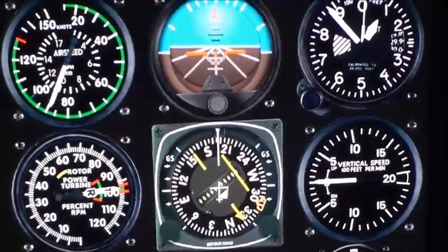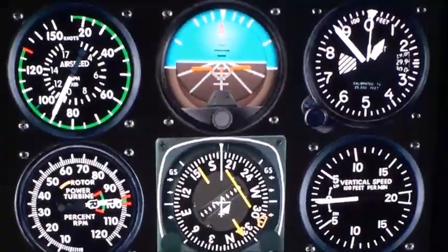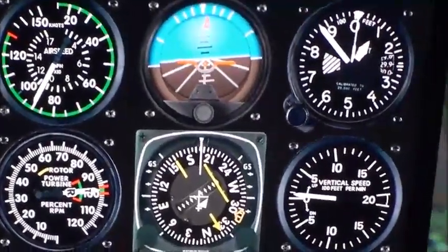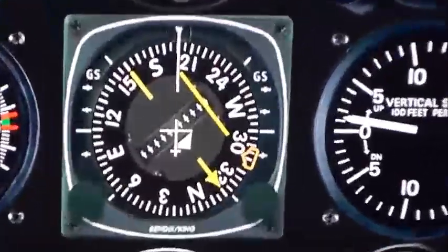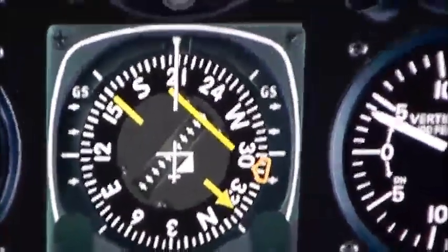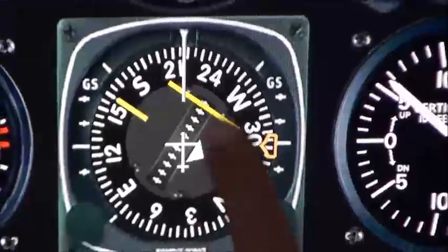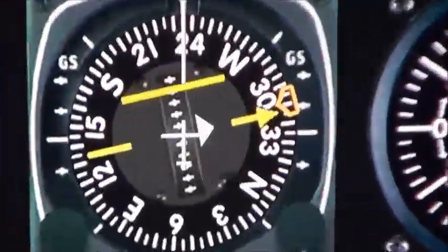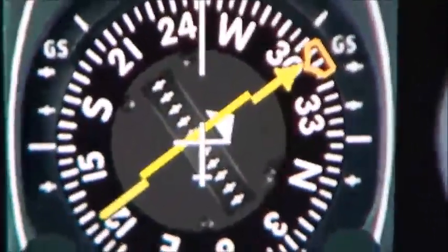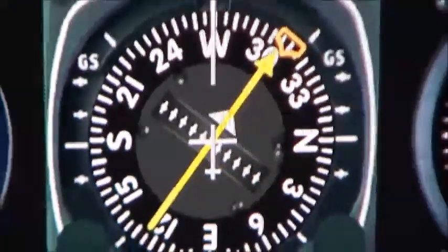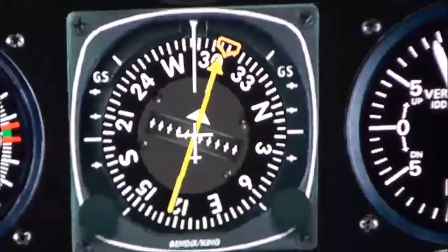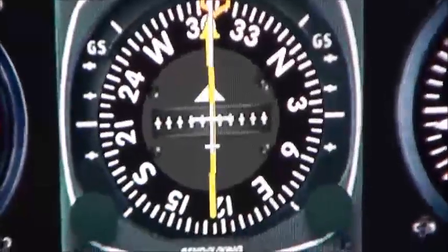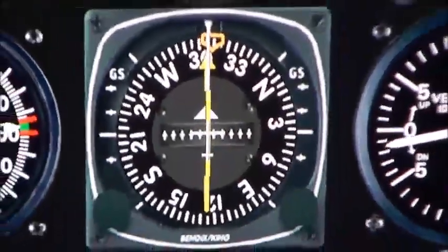And we'll go out, and we need to show the VOR and ILS change of 1 degree for VOR and a quarter of a degree for the ILS. Okay, so I'll tune a VOR into my Nav1 radio here. I'll head towards that VOR, and there's our course deviation indicated. So now we're heading directly towards the VOR.